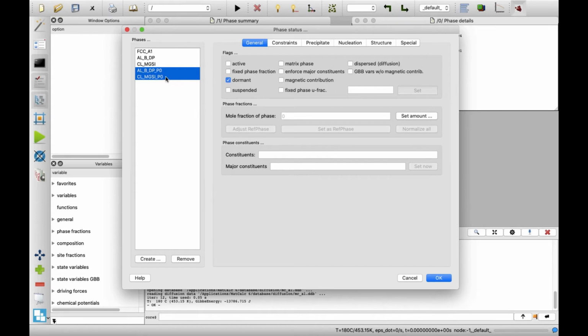The co-cluster phase is difficult to model properly, because it is on the border of precipitate definition. On one hand, the clusters could be still regarded as a bunch of solute atoms that come together, on the other hand they still comprise a part of matrix. So, in our approach we treat these as precipitates. In order to represent their high number density, we have to modify the interfacial energy.